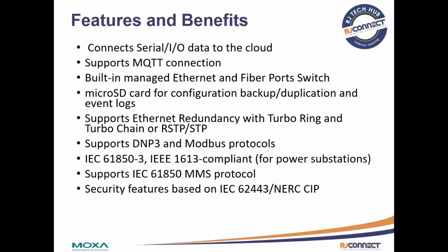Again, it supports the IEC 61850-3, the standard for power substations, and is also compliant with the IEEE 1613 standard. It also supports IEC MMS protocols and GOOSE messages and protocols. And the last one is the security feature based on IEC 62443. This one is for the cybersecurity feature.